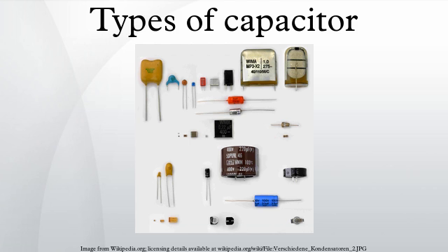Capacitors are divided into two mechanical groups: fixed capacitors with fixed capacitance values and variable capacitors with variable or adjustable capacitance values. The most important group is the fixed capacitors. Many got their names from the dielectric. For a systematic classification, these characteristics can't be used, because one of the oldest, the electrolytic capacitor, is named instead by its cathode construction. So the most used names are simply historical. The most common kinds of capacitors are: ceramic capacitors have a ceramic dielectric.